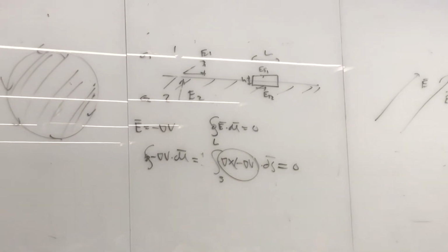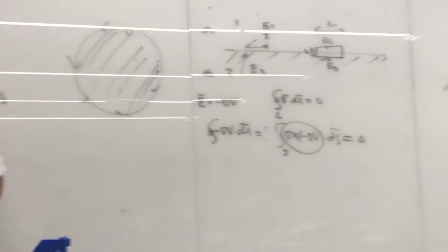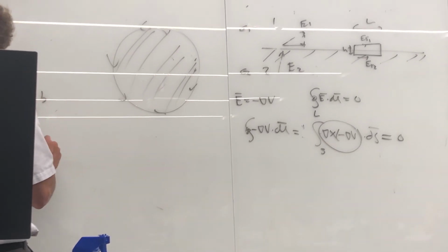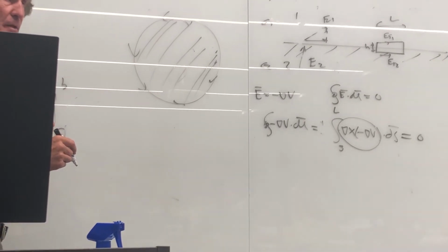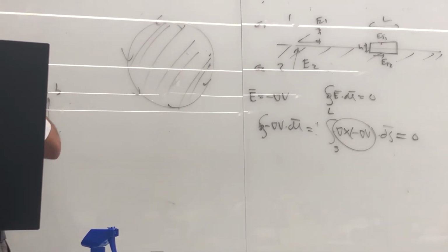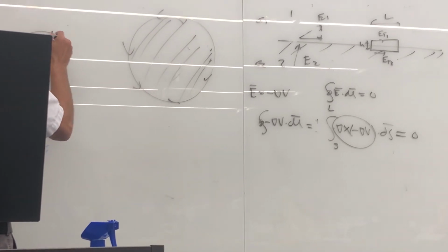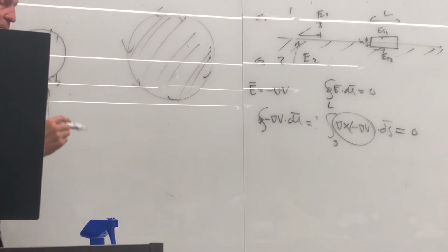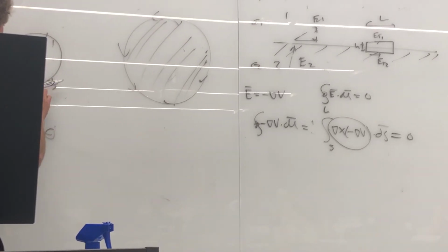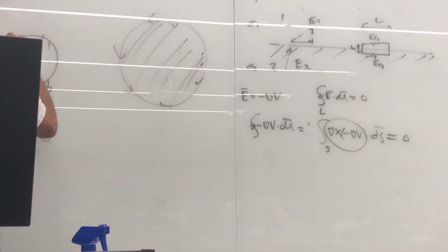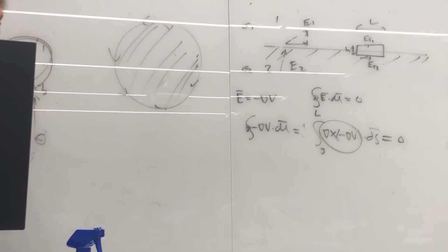If you have 2 points, A and B, and I have a meter, and I put the plus lead here, and I put the minus lead here, I can measure a voltage between those, right? But if I start here, end up here, when I do the integral of E dot dl, I would get the voltage between A and B. Do you agree with me? Well, what about A going to A? What if B becomes A? If I start at A and I go all the way around and I put my meter's B lead right here, how much voltage do I measure?